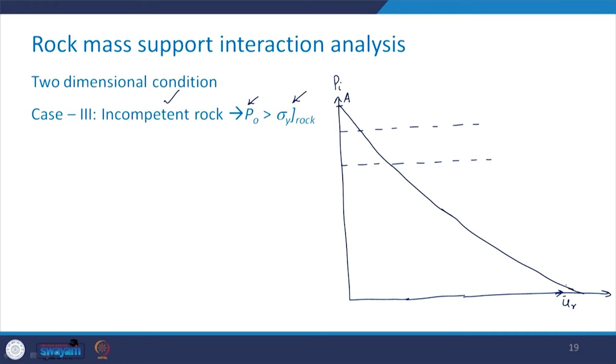See, the response is like that. Okay. So, here in this case from this to this zone, it is the linear elastic deformation. However, from this point B to this point C, this much is non-linear, but it is still in the elastic range.